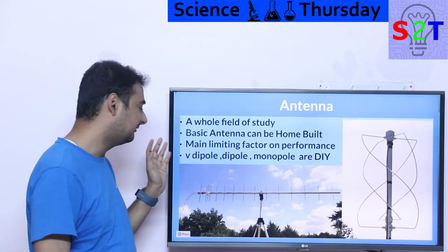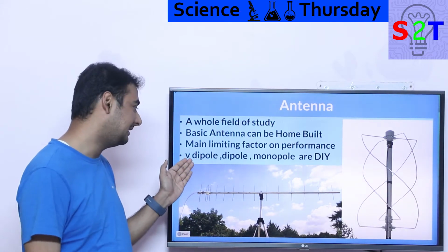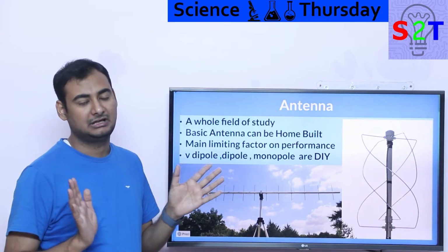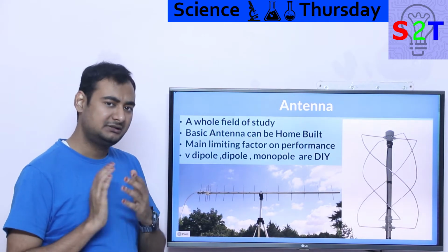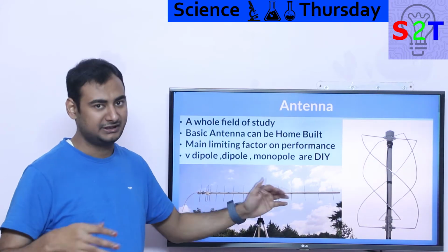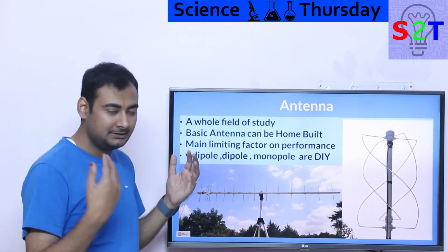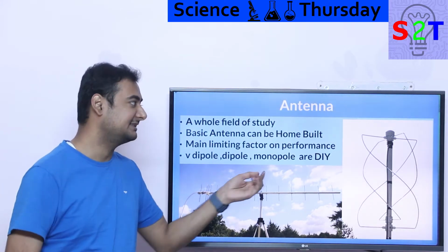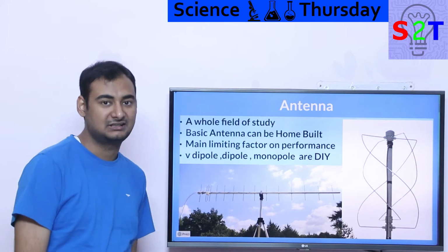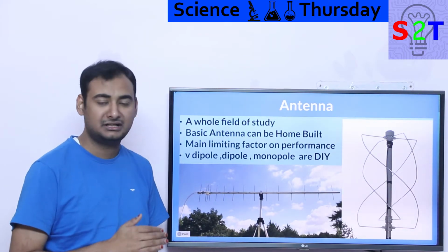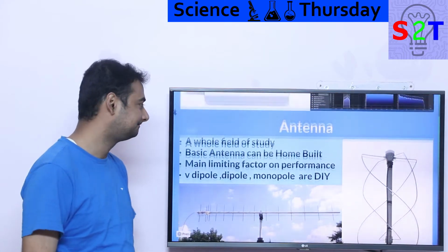You get the point. So you have very simple systems like dipoles, monopoles. All things are DIY. You can do that yourself, but be mindful, it will take time. You will not just start like, oh, I'm going to make one and everything's going to work fine. No. Even people who have successfully got it to work will talk about packet loss and all that jazz. There is a reason why a proper antenna costs such a large amount of money. But the antenna is your first starting point. If you don't have a good antenna, do not blame the SDR.